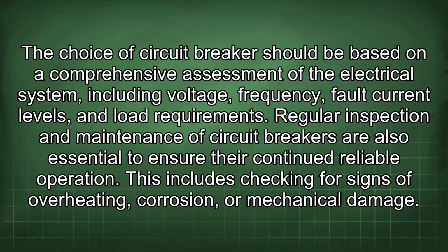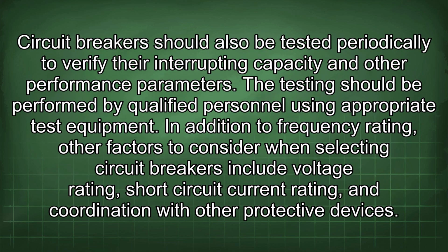Regular inspection and maintenance of circuit breakers are also essential to ensure their continued reliable operation. This includes checking for signs of overheating, corrosion, or mechanical damage. Circuit breakers should also be tested periodically to verify their interrupting capacity and other performance parameters. The testing should be performed by qualified personnel using appropriate test equipment.